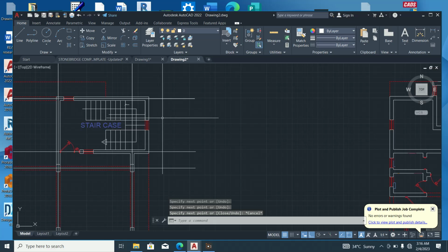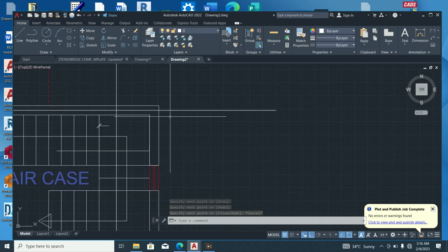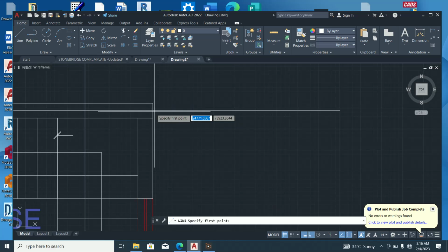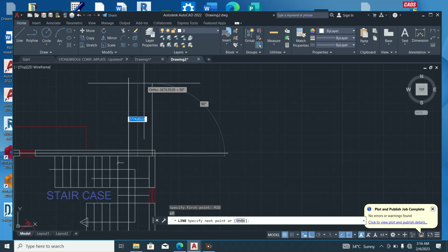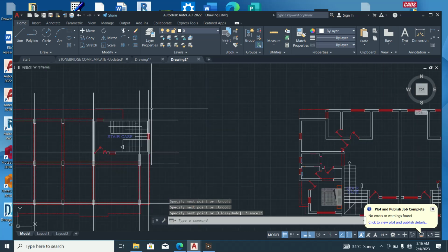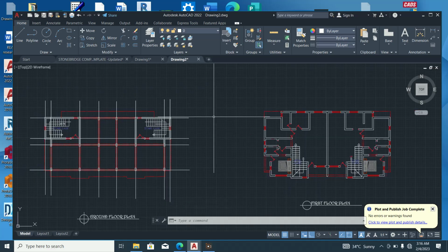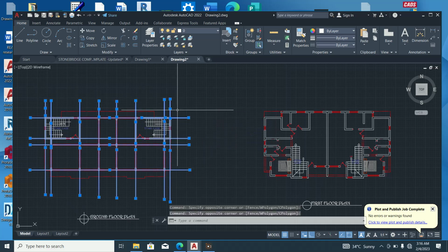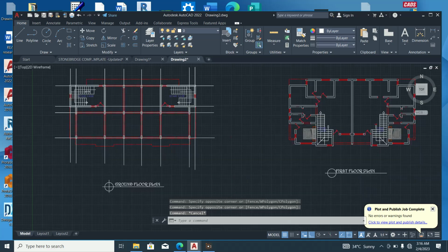Then let's do the last one. If you don't have a perfect triangle, a perfect square, you can just create a perfect square by yourself by doing what I just did here. Then pick a line, type mid, click on OK, go up and go down. As you can see, I'm done with the grid line for both the horizontal and the vertical axis for the ground floor.